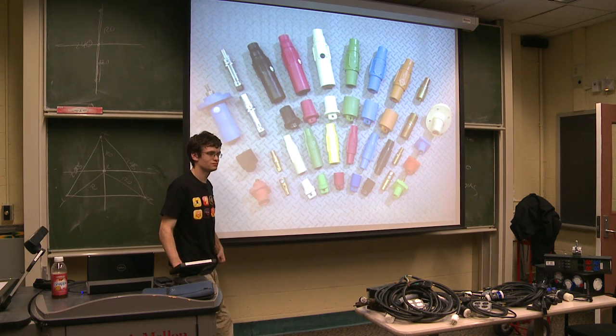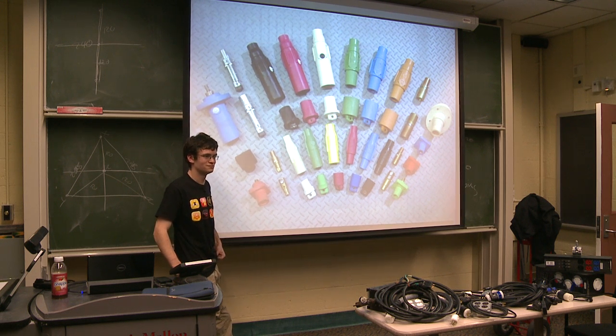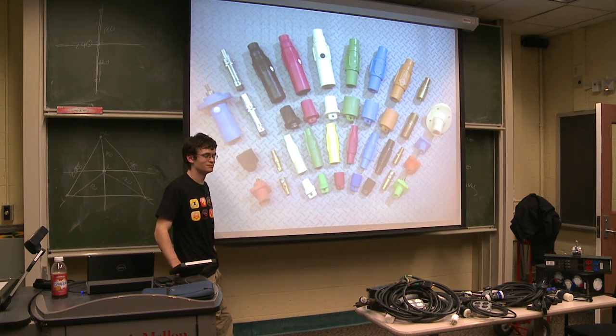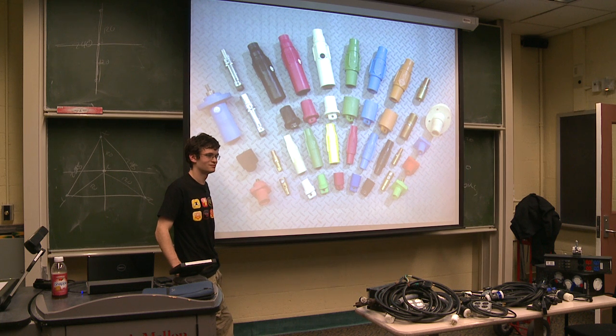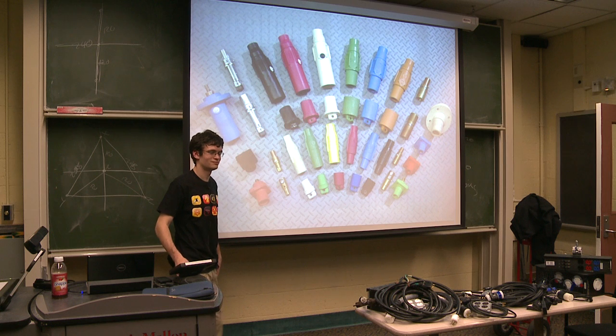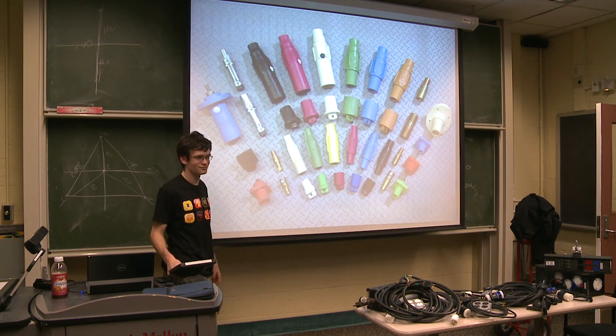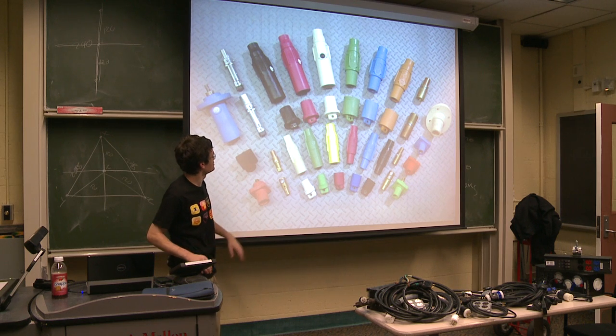There's a couple other versions of three-phase that you didn't talk about. Yeah, like a delta where you actually ground one of the corners, and there's two hots and a grounded connector, but you still get three-phase. Some of that stuff just gets weird. We're sticking to the nice easy 120/208.